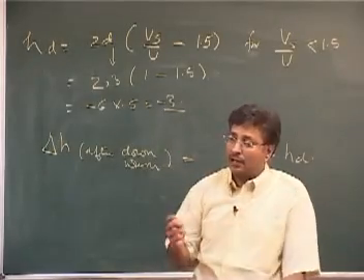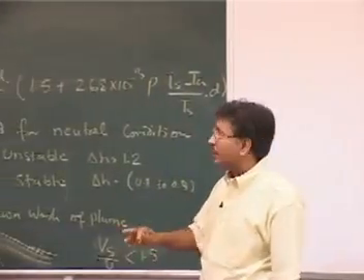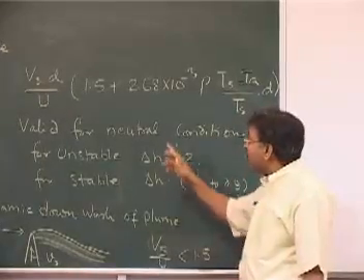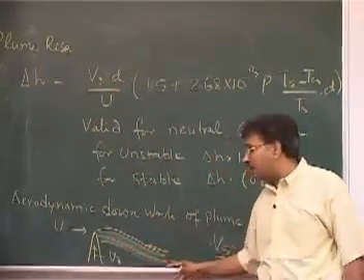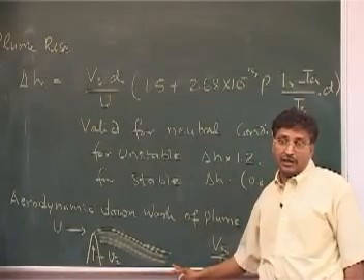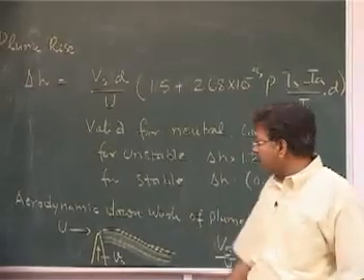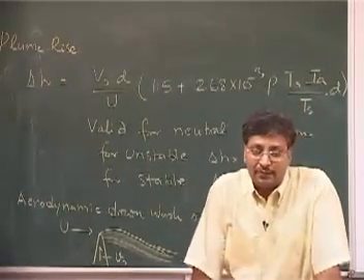This can be very important because you may have designed a good temperature and a good diameter, but if your exit velocity is not properly designed, you will unnecessarily cause serious problems to the people living in the area. One time we encountered this for a sulfuric acid plant.